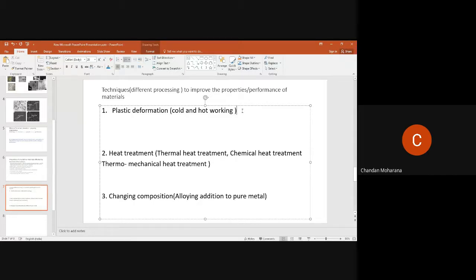Okay, what is recrystallization? Anybody tell me what is recrystallization? The temperature at which strain-free grains are produced. Very good. The temperature at which new strain-free crystals form. Re means again, crystallization means formation of new crystals or new grains. That's why the name is recrystallization. So formation of new strain-free grains. Where do they start to form basically? In which area of a material do they form? Grain boundary, basically, where two or three grain boundaries are meeting, right?